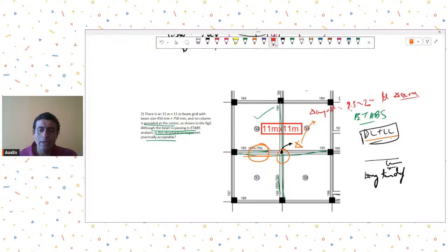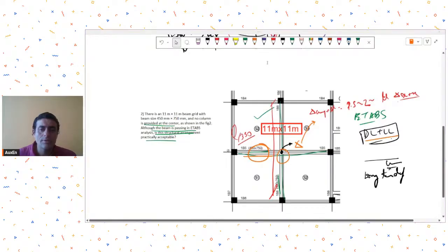So take that deflection value and ensure that it is less than the codal provisions, let's say L by 350. L by 350 is what is given in the code. Understood? Yeah.